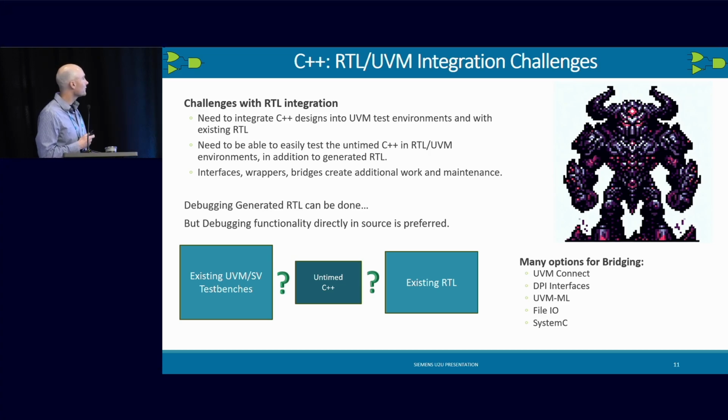The next one is the RTL and UVM integration challenges. When we're abstracting, there's almost always a reason that we have to interface back into existing RTL, as well as UVM test benches for verification, and SystemVerilog test benches.